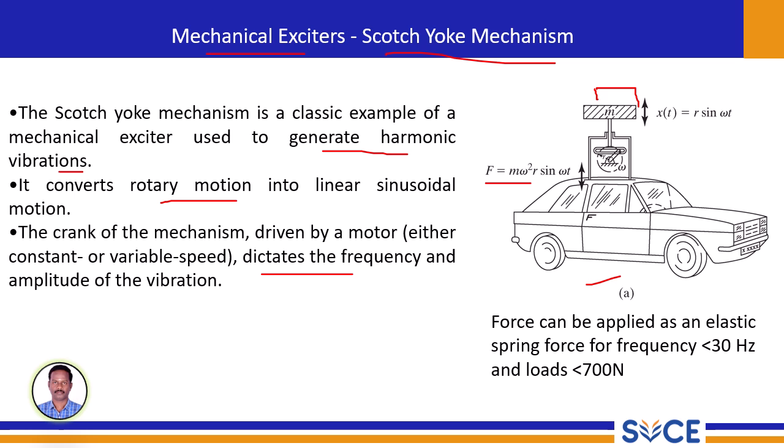Note, it is very important: mechanical excitators use elastic spring force and are particularly suitable for low frequency applications, that is typically below 30 Hz, and loads which are under 700 Newton.